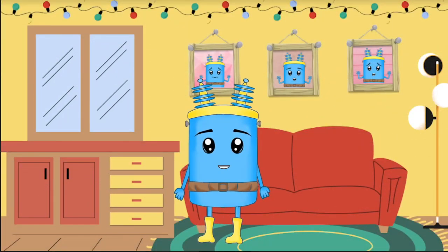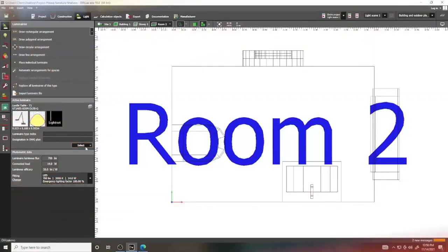And with rendering being finished, now we can see the lux or illumination of the given room. And then, if we want to explore the view of the room, we will just click Results Overview. Just remember, if you want to add more luminaires and lamps, just go to the active luminaire, drag, and then drop. Now let's design the rest of the rooms.